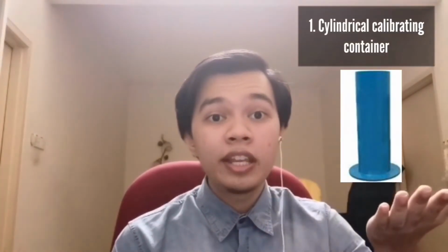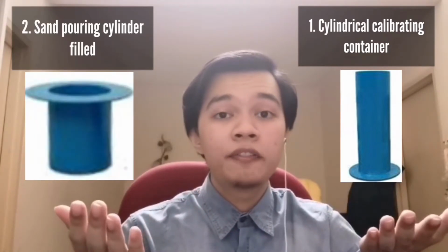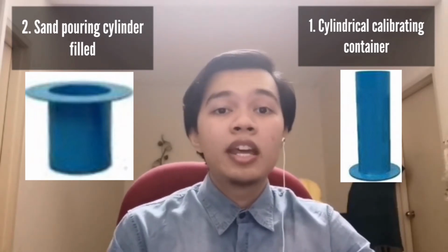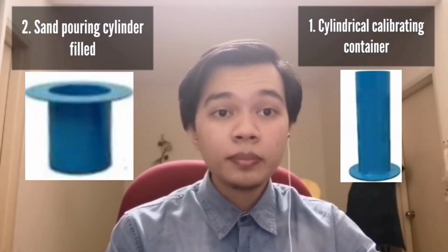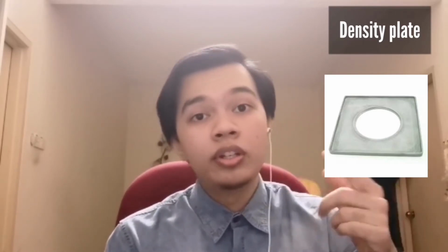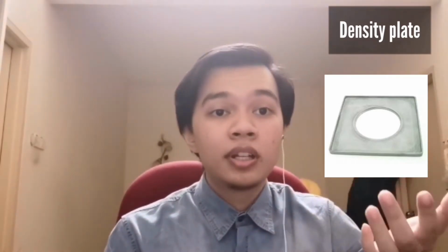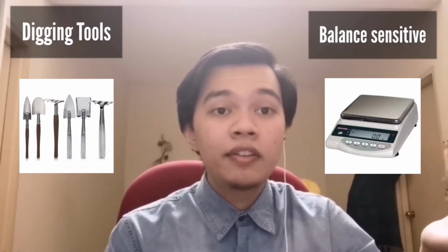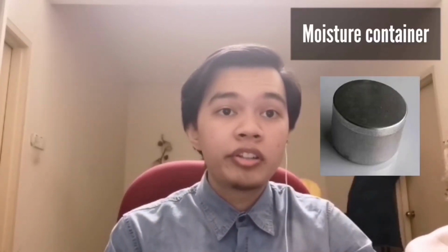Okay, what apparatus do we use for the experiment? First is a cylindrical calibrating container and a sand pouring cylinder filled with uniformly graded sand passing through number 20 and retained on number 30 sieve. Next is a density plate with a center circular hole of diameter equal to the diameter of the pouring cone. Digging tools, a sensitive balance, spoon, metal tray, brush, moisture container, and last but not least, an oven.